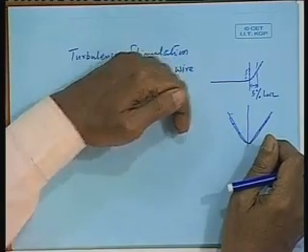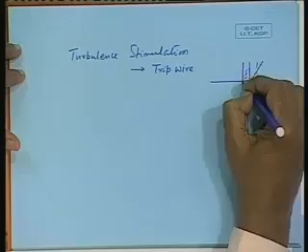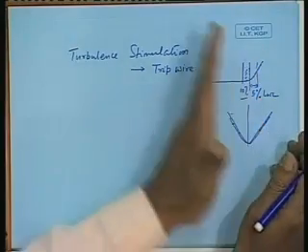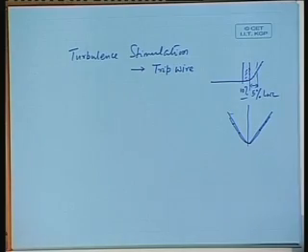So, the turbulence that you created may be suppressed again and laminar flow may take over. So, it is common practice to use not only one, but maybe 2 tripwires, at another maybe 10% distance or 7.5% after; it depends on the type of model, type of fullness, etc.